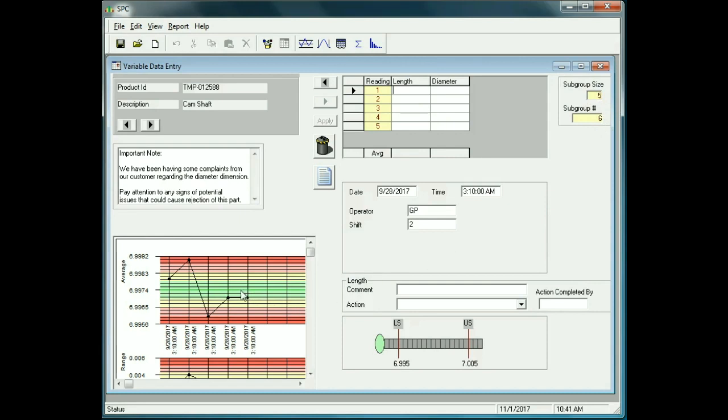The coloring here is related to zones. The green zone is an acceptable area for fluctuations in averages. Once in a while, you will have averages in the yellow and the pink zone. The red zone is actually beyond the expected amount of variation for averages. We would call that an out of control point, statistically speaking.